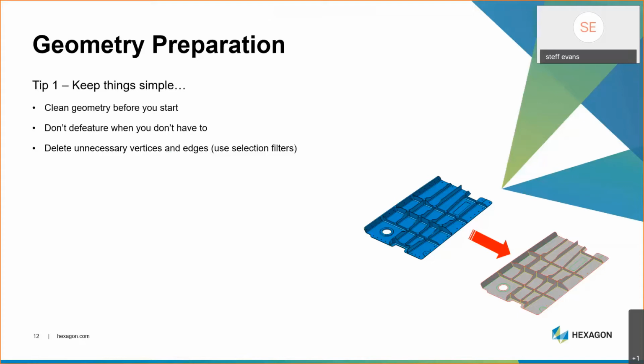We're ultimately going to be generating a mid-surface, as it were. So there's little point in spending a long time defeaturing solids if the target model output is surfaces. Okay, and then during the manipulation, it's probably good practice to delete unnecessary vertices and edges, to try and simplify the geometry as much as possible to get us back to our bare bone surface for mesh development.